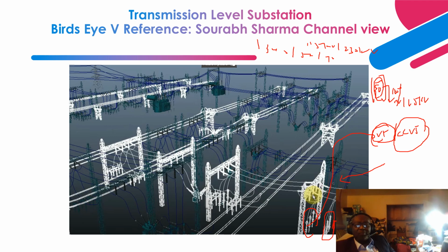On the other hand, capacitive coupled voltage transformers, or capacitive voltage transformers, utilize capacitors to achieve a voltage divider because of the high voltage applied. So we have 115 kV, 230 kV, 345 kV, 500 kV, or 765 kV, and the capacitance is arranged in a voltage divider configuration to achieve a lower voltage.